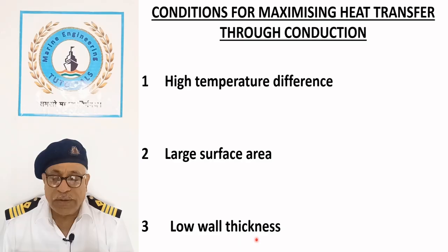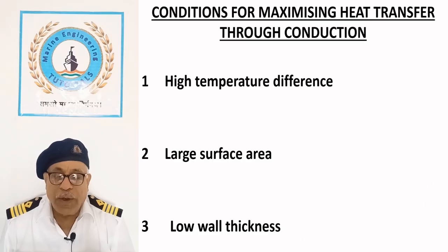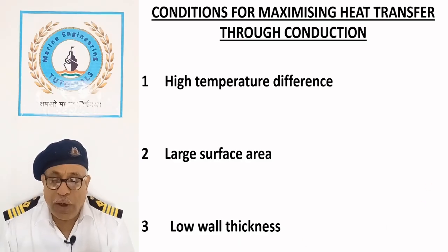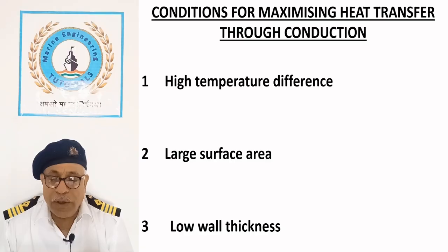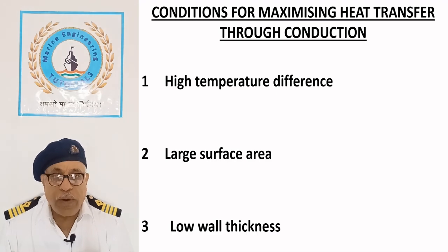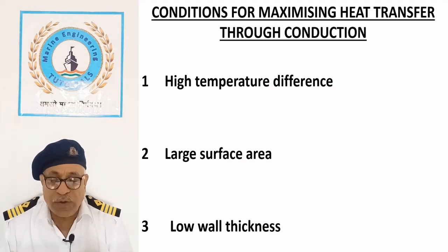Low wall thickness. Heat transfer is inversely proportional to the wall thickness of the heat exchanger. Therefore, the tube wall thickness should be kept as thin as possible while still providing adequate strength to safely withstand the internal and external pressures during operation.